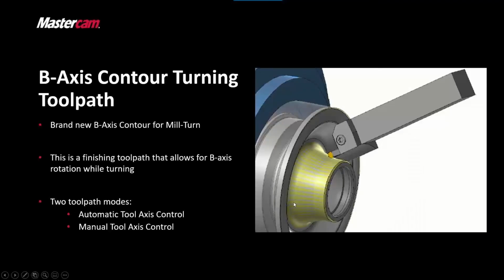All right. So next subject I want to talk about is the new B-axis contour turning toolpath. What this does is this gives users with a 4th and 5th axis capability of tilting to make a toolpath that tilts the tool along a curve. So this is a finishing toolpath, and I want to cover the 2 modes that are used with it: automatic tool axis control and manual tool axis control. And we're going to take a dive onto a part that does some ID and OD turning with some B-axis involved.